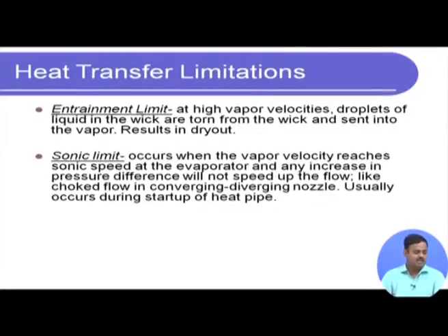And the last one is the sonic limit, which also occurs because of the very high vapor velocity, where it reaches velocities similar to that of sound, and that can lead to choking and a lot of undesirable effects as is shown here. It can sometimes happen during startup of the heat pipe.